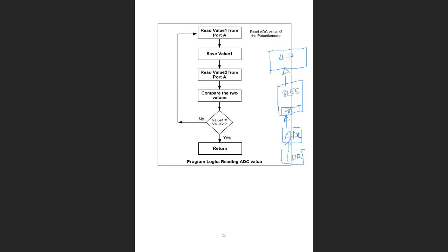And then definitely we have given... So as we already know, the microprocessor normally does not directly connect to the input output system, the external system. It connects through the 8255 IC, right? So for example, port A is used here to get the input data from the analog to digital converter. So port A is used to receive this digital data about the light brightness. That means port A is an input port to get the digital data of the sensor.